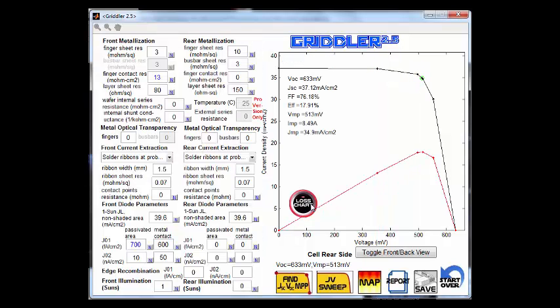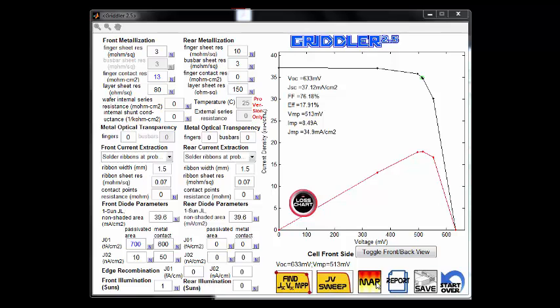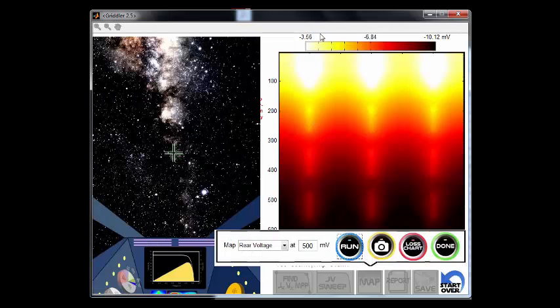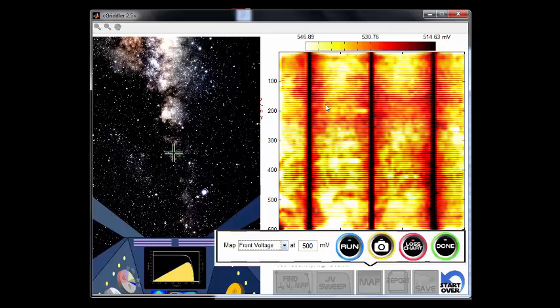So obviously here the fill factor has dropped to 76.18%, down from 78.1% for the cell tested in an IV testing condition. And that's obviously due to this extra series resistance introduced by the ribbons. And now, if we go near the MPP and rerun the simulation of the voltages, we see a different pattern. On the rear side, we can see the effect of the voltage drop in the ribbon. On the front side, it's not as obvious because of this kind of grain contrast, but there is a gradual voltage drop as we move current down the ribbon.